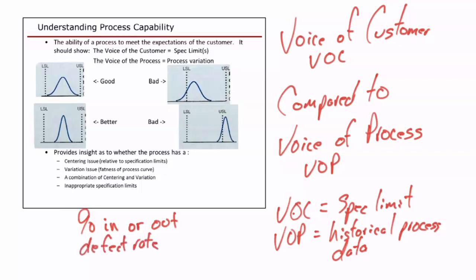Sometimes in production and manufacturing environments, because you're dealing with such a consistent process, the way that we count these defects is defects per million opportunities. Another way to take a look at how well your process is performing is to measure the number of standard deviations that fit inside of spec. We, in the end, call those sigma levels of performance. Examples of sigma levels of performance, I'm operating at a Six Sigma level of performance.